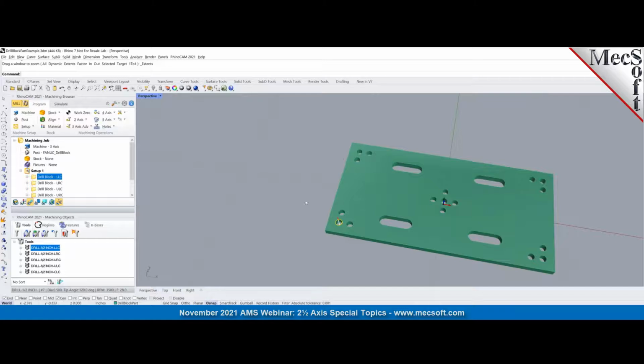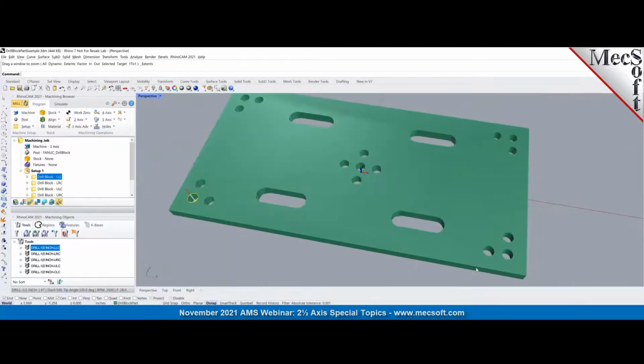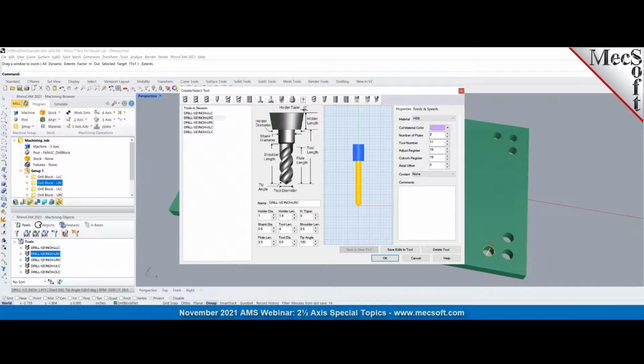So let's talk about the lower right corner. In this particular case, we have to turn on tools 1, 2, and 4. And 4 is the binary code 8. So 8 plus 2 is 10. 10 plus 1 gives us 11. So now I've already got a tool, the lower right corner, I'm calling it the LRC, and it's got 11. I've got a tool number 11 encoded.